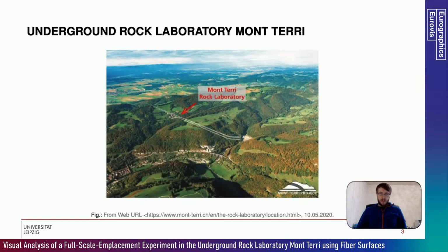In this region the predominant geological material is opalinus clay. In detail, research was being conducted into the storage of radioactive waste in the opalinus clay. This is suitable for the storage of radioactive waste due to its favorable physical properties, its low permeability to water. The water transport of radionuclides into the biosphere can be practically excluded, and this is therefore an alternative to disposal in crystalline or salt rock.